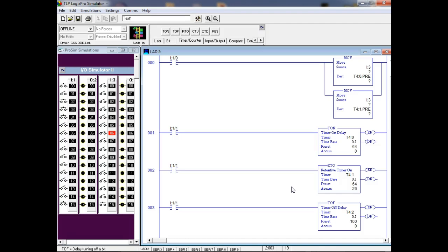That was cascade timer to increase the time. Increase the time available. Yeah. That was what it was in PLC 1. So that's about the only time we would cascade timers. But you got to understand that the explanation they used is I took one that was timed for 10 seconds and I cascaded that with one timed for 20 seconds. Why would I do that? I just have one timer for 30 seconds, right? You understand? But all they was trying to do is demonstrate cascading timers.